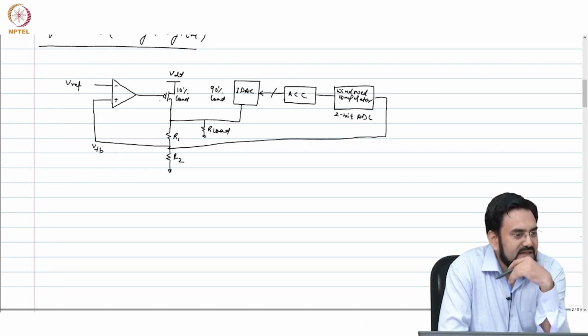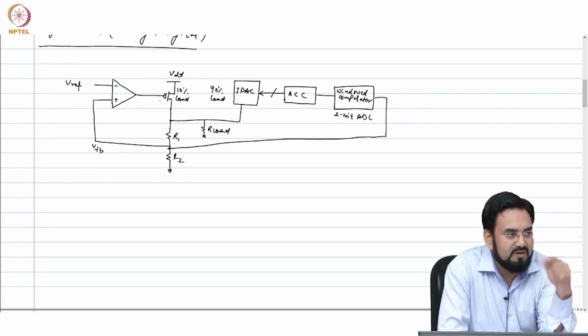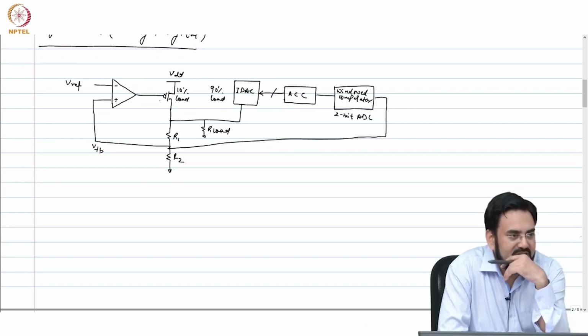So that's one way, and that threshold you can set lower also, that doesn't matter as such. You can set at 500 microamp so that you don't go for full 1 milliamp, because you don't want to saturate that. That's one way.